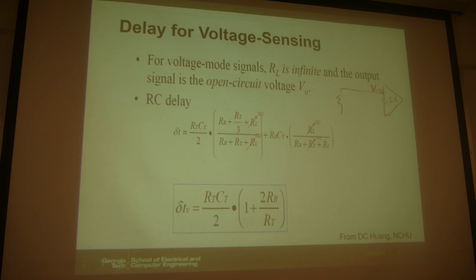If you look into the sense amp from here, ideally when you measure voltage, if you think about the voltage meter, you have something in parallel with your device under test. You have the voltage meter in parallel with that, and that voltage meter input will take no current. So it's like the resistance is very, very large, like an open circuit.